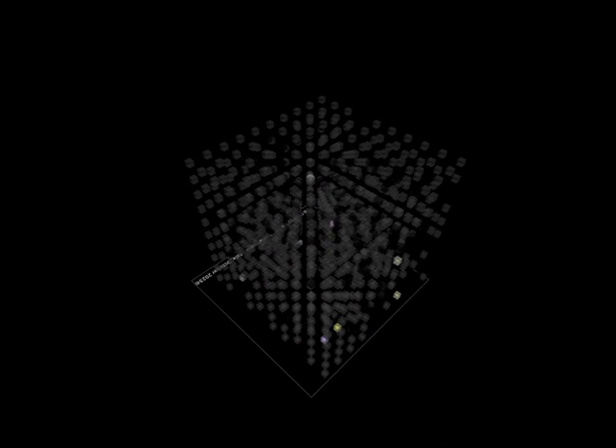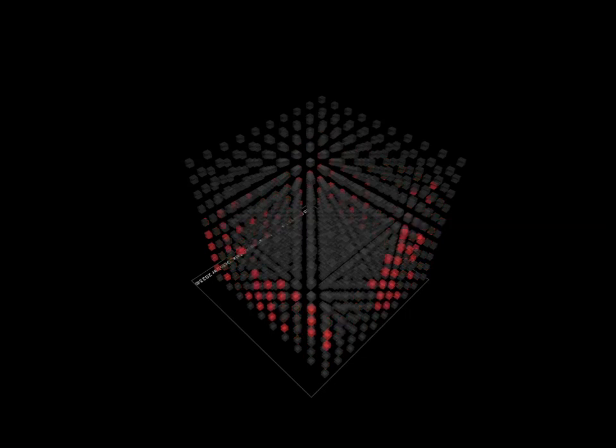You are probably thinking, what happens when the counter reaches 7? That would mean that the output on port B is 8, 1000 binary, on the last iteration of the for loop. Only the first 3 bits of port B are connected to the 74HC138. So when port B outputs 8, or 1000 in binary, the 74HC138 reads 000 in binary, thus completing its cycle. It started at 0. The 74HC138 now outputs the following sequence: 1 2 3 4 5 6 7 0, thus giving a change from low to high for the current latch according to counter I.